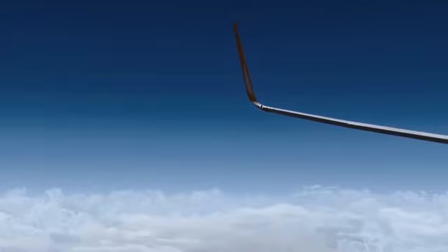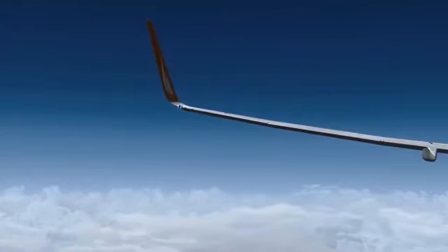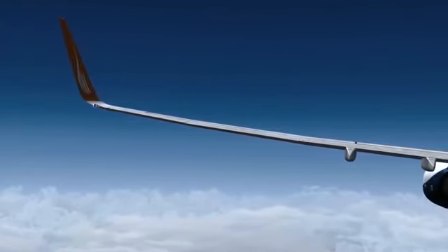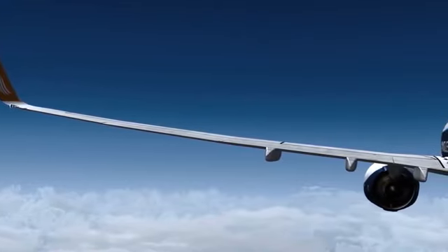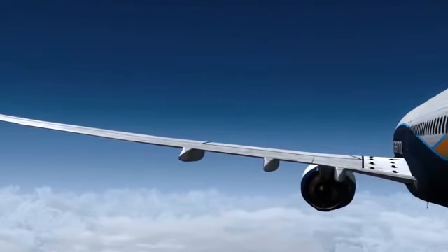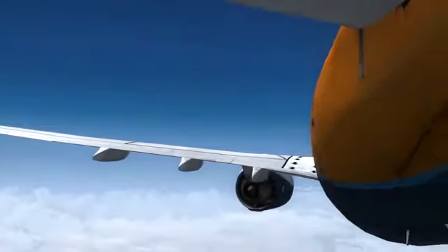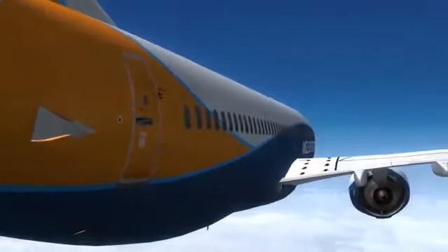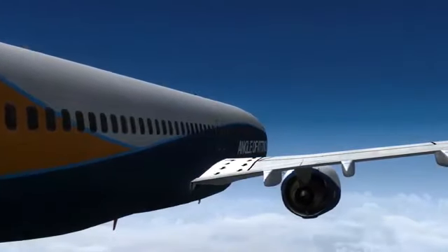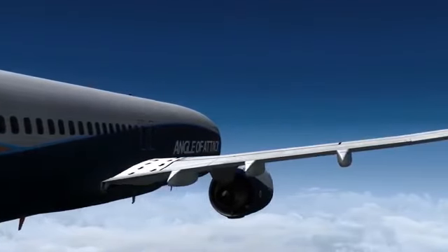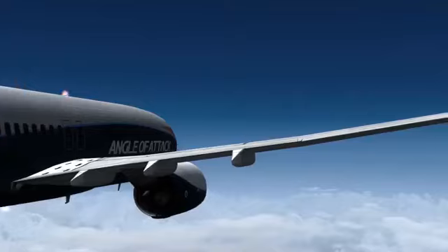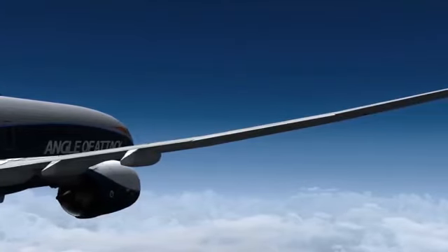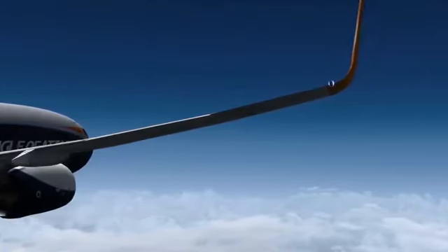We all know that the chances of this occurring are minimal. However, the redundancy must still be built in to make the systems more reliable and dependable. Both batteries are always kept at maximum charge by a main and auxiliary battery charger, powered by the AC power system. In case the batteries were ever to drain on ground, it takes nearly 3 hours to charge the batteries from zero charge to an operational level.